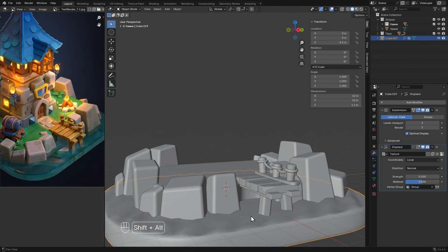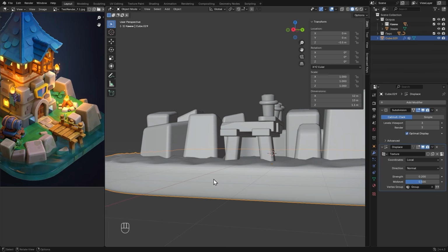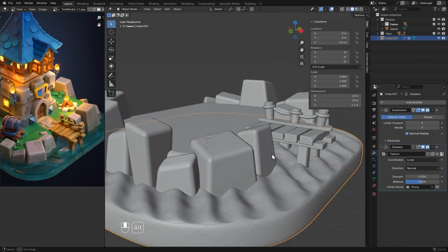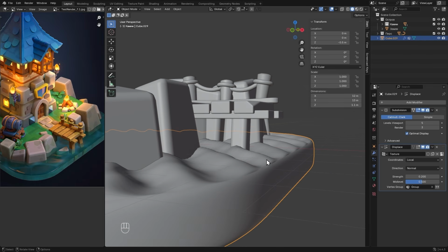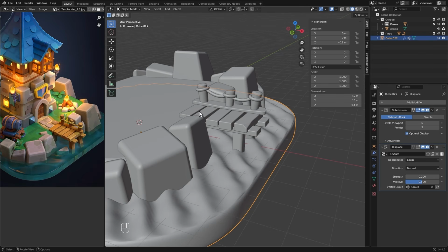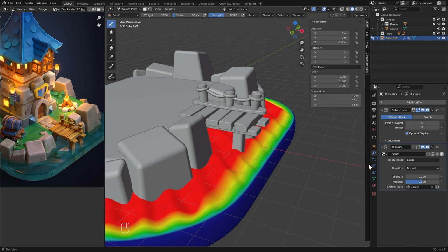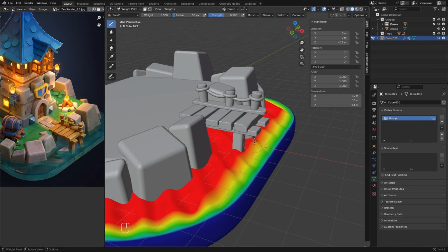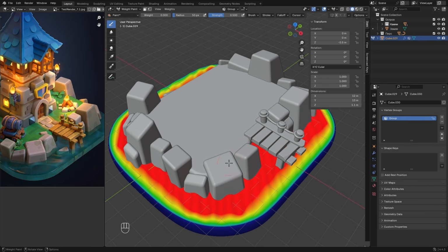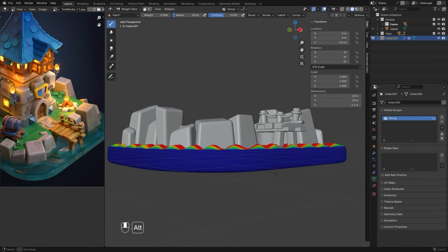Let's get closer to the object and look at its detailing. Right now it's very low, so in the subdivision settings, we'll increase the Levels Viewport parameter to 4 or 5. You can also notice that at the edges, where the ripples end, they cut off very abruptly. To fix this, we'll switch to the Weight Paint mode. This is what we were creating over here. Right now they look like this. Where it's red, the modifier is applied very actively. Where it's blue, it isn't applied.